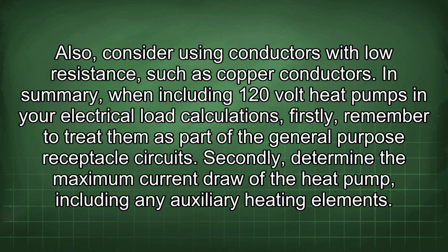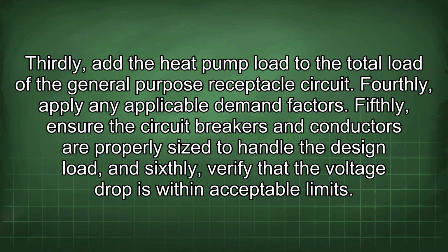In summary, when including 120-volt heat pumps in your electrical load calculations, firstly, remember to treat them as part of the general-purpose receptacle circuits. Secondly, determine the maximum current draw of the heat pump, including any auxiliary heating elements. Thirdly, add the heat pump load to the total load of the general-purpose receptacle circuit. Fourthly, apply any applicable demand factors.